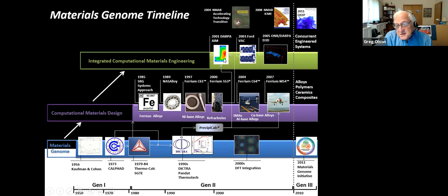And this was to go beyond the initial design of material to address the full materials development cycle, which is the goal of the Materials Genome Initiative: the linking of microstructural models to macroscopic process simulators to accelerate process optimization at the component level, and very importantly, to simulate manufacturing variation within allowed tolerances to give accurate forecasts of minimum properties that become the design allowables that a material user can depend on. And this was to replace statistical inference with probabilistic science that could greatly reduce the amount of experimentation necessary to get a material all the way to certification.